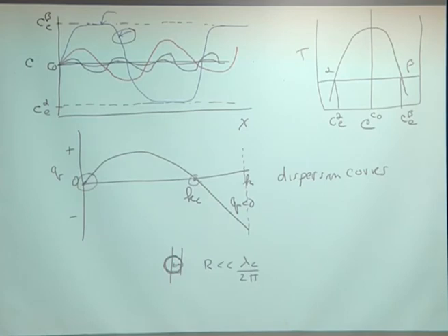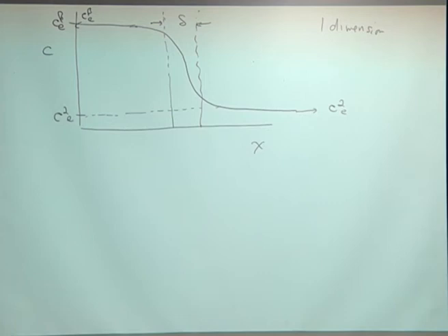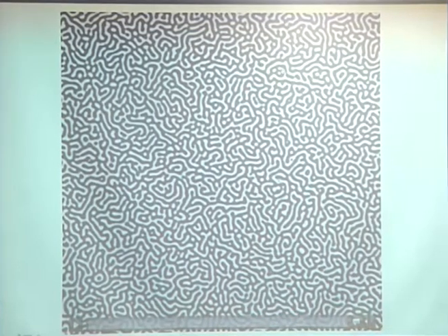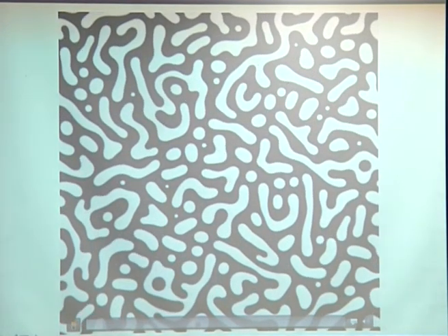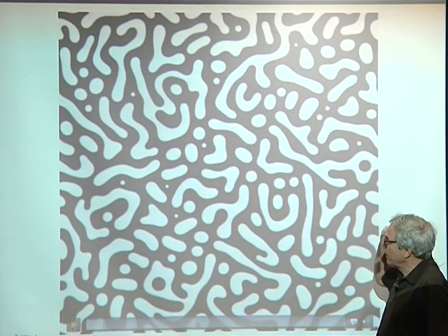that's the advantage of the Cahn-Hilliard equation and of a phase field model itself: it captures the limit where these are the equilibrium compositions, and you have an interface in between. And so these interfaces can move, they can join together. That's not a problem. You probably saw that in the 2D calculations. Let's look at this one again. Okay, so now it's phase separated. You have particles with composition nearly equal to the equilibrium composition of beta, and the equilibrium composition of alpha.